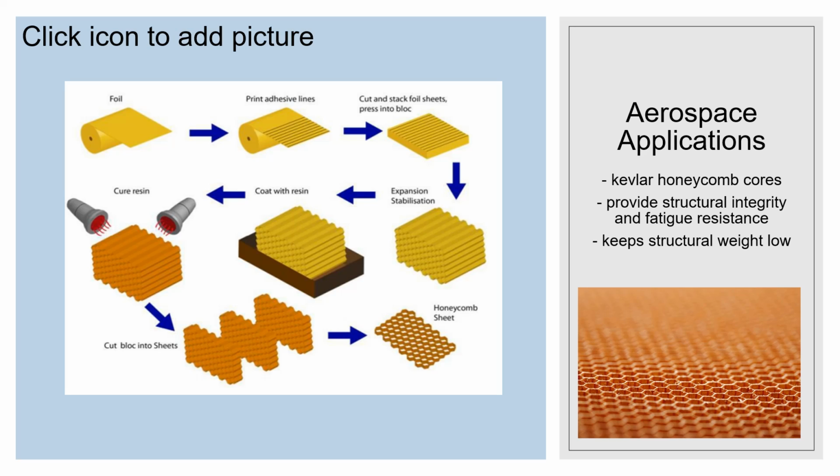In the next stage, the structure is dipped into a phenolic resin bath that evenly coats the walls and is then placed in an oven to be cured, then weighed and inspected. Often a cycle of dipping, curing, and weighing is necessary to achieve the desired thickness for the specific application. Finally, the honeycomb blocks are cut into honeycomb sheets through the final machining processes.